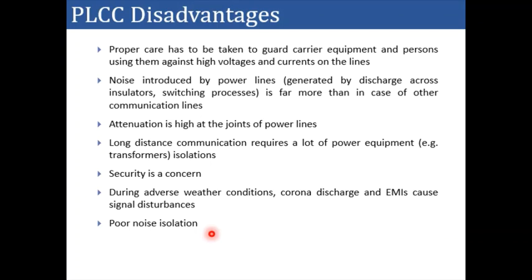Further, there are a lot of concerns with respect to the attenuations because whenever we have the joints in the transmission line, the data will get severely attenuated. So because of these challenges, PLCC is not effectively utilized for long distance data communication.